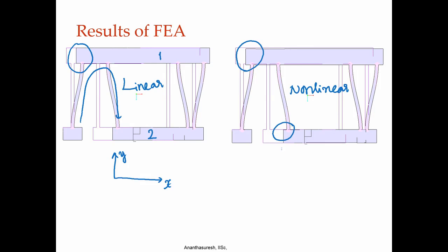Now here you do not see that. So, this one comes down relative to that one, this actually goes up, these two things cancel each other and there is no motion. So, if you do linear analysis, we are actually misled that this platform is not moving in the y direction at all. So, it is important to notice the effects of nonlinearity.